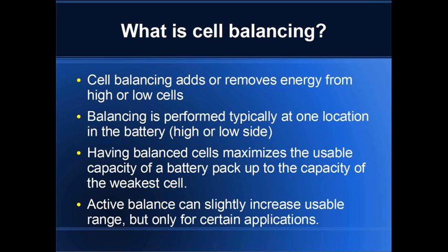And so usually for the cost benefit, unless you're working with really large batteries, it may not be terribly cost effective to do that. That said, there are certain applications where that makes sense. Secondhand electric vehicle battery packs, which are ones that have been used in their primary life for an electric vehicle, and they're no longer good enough to run a vehicle, but they might be good enough to do energy storage. Sometimes that's a good application because those cells are going to be all over the board as far as capacity that they have, and you need to be able to handle failures more gracefully in there.